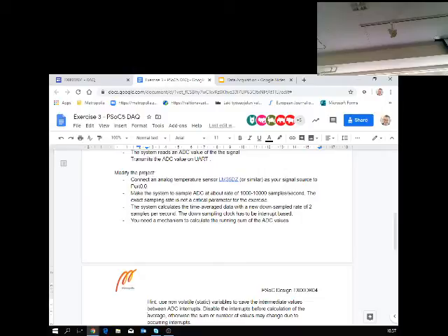The extremely dangerous thing for these circuits, actually this real sensor, is to reverse the polarity. Old school electronics teachers know that with this kind of package, the pin out is given from the bottom side, not the top side as for other integrated circuit packages, since this is an old transistor type of package.